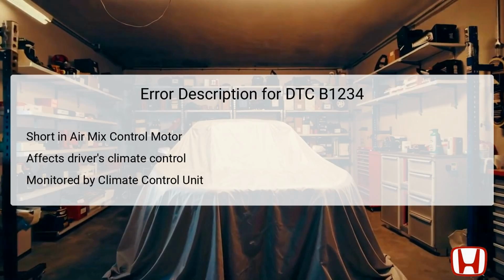DTC B1234 signifies that there is a short circuit in the air mix control motor circuit, specifically affecting the driver's side. The air mix control motor is responsible for adjusting air temperature produced by the climate control system in response to input from the vehicle's environment sensors. Located near the climate control unit, this motor plays an essential role in providing the right temperature as configured by the driver. The climate control unit continuously monitors the motor's input voltage.